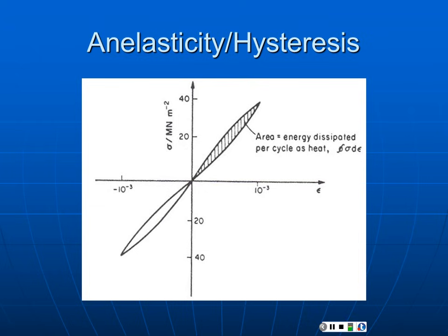So your spring isn't springy, the ball doesn't bounce, because the energy of compression is dissipated internally, and it's dissipated as heat. And so materials warm up. And we can use this. We have some really high loss materials where the unload curve may do something like this, and you may have 80 or 90% of the energy that went in disappears. And so you build rubber balls that don't bounce, shoes that are not too bouncy, that absorb shock, so on. And so this is called hysteresis, or anelasticity, that is not elastic, the absence of elastic behavior, and we get energy dissipation in the material.